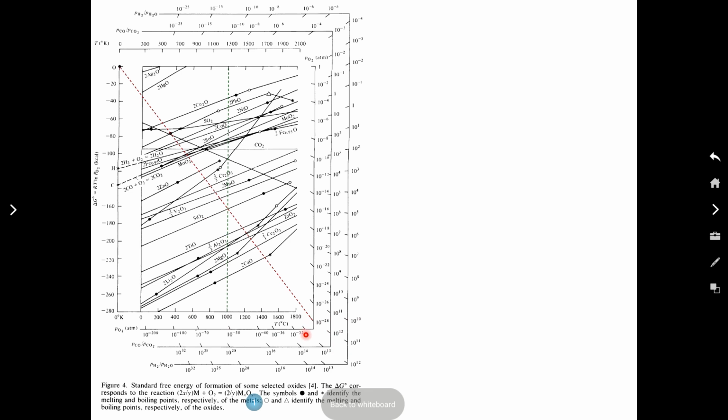If you exceed that, silicon will oxidize at that temperature and form silicon dioxide. Or you can turn around and say, if I make a stack of silicon and silicon dioxide mixture, you can just take powders of silicon and silicon dioxide, mix them mechanically into a two-phase mixture, pack it in a vacuum chamber and heat it up to 1000 degrees Celsius.